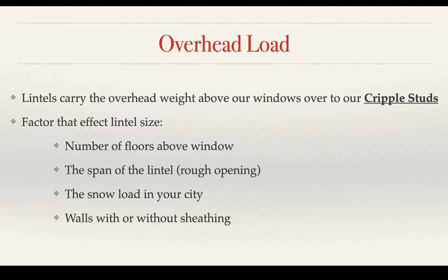So things that affect the size of our lintels would be how many floors is the lintel carrying. So we know that our building has to transfer weight from all the way at the top, all the way into the ground below. So through the roof, through the walls, through the foundation, through the footings, into the ground, right? So if our lintel is on the first floor and it's carrying 2 floors above it and the roof, it's going to be different than if the lintel is just carrying the roof.